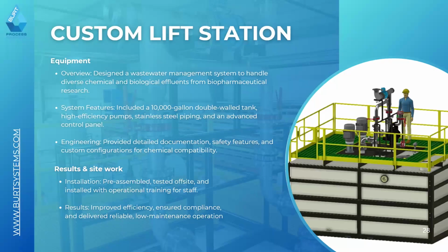That itself could be its own webinar, some of the different pH probes that are out there. What I do like to recommend sometimes is redundant pH probes. While pH sensors are considerably smarter than they used to be, say even 10 or 15 years ago, where you can pull alarms, you can pull calibration data out of them, things like that. There's a lot of different, and a lot of that is what your plant standard is, which is what I would probably defer to, although I could obviously make some recommendations if there's a more specific question related to this offline.